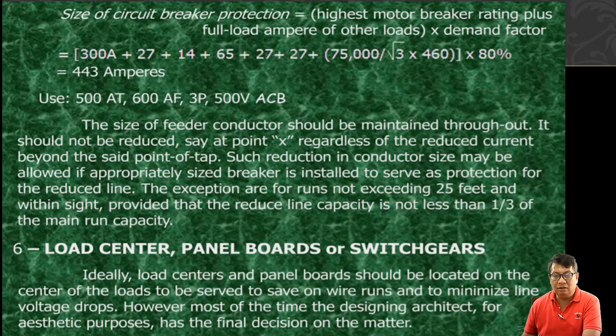Now, let's proceed to load center, panel, boards, and switchgears. Dito po na, we have to determine the load center. So, what are the necessary design that you are going to do in that load center? So, ideally, load centers and panel boards should be located on the center of the load to be served, to save on wire runs and to minimize the voltage drops. However, most of the time, that is designing architect for aesthetic purposes, the final decision of the matter.